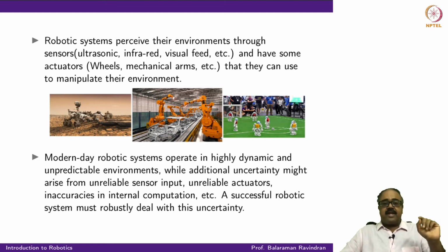And if anyone has tried anything with robots, even a simple line following robot, you know that the actuators, even a simple gear system that turns wheels, are not completely accurate. It's going to take quite a bit of calibration before you figure out, if I say move 1 meter forward or one foot forward, how much does the robot actually move. So that is going to take a little effort to figure out.